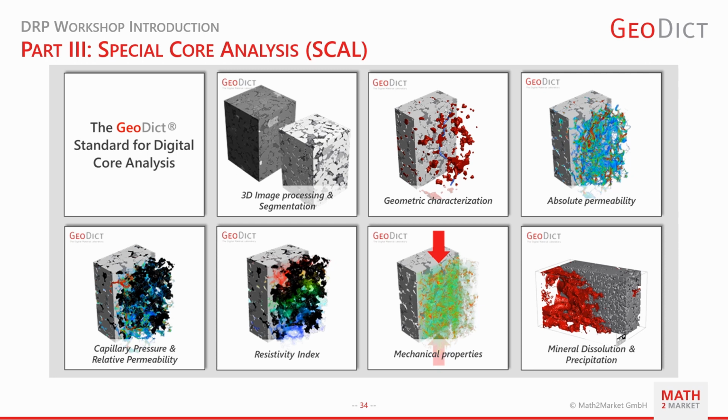First, we will compute a digital mercury intrusion capillary pressure, a digital MICP. Then we continue with a drainage computation, where we will have a look at the settings for computation of the relative permeability based on the result of our previous drainage computation. Finally, we will run the new forced imbibition capillary pressure GeoApp to predict a complete capillary pressure hysteresis cycle.